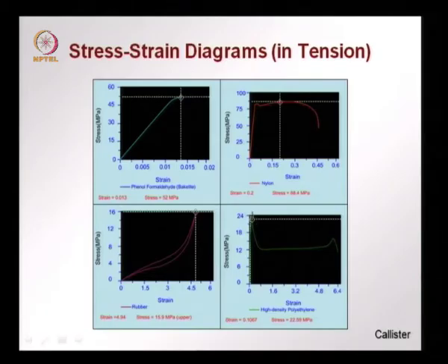This is where all the chains start being aligned in a certain section, followed by a drop and some amount of plastic behavior, where the chains start resisting load. So, you have an elastic part, a peak occurring, some amount of drop, which could be called softening, and then a plastic response over a large strain.